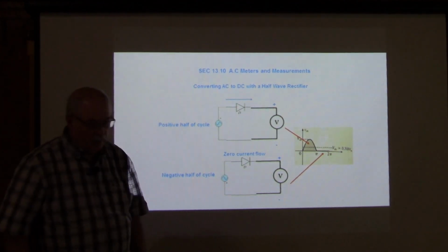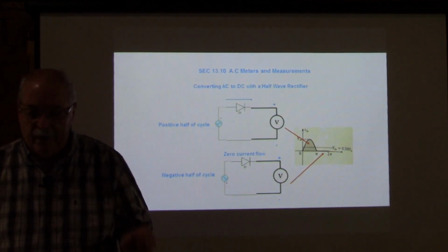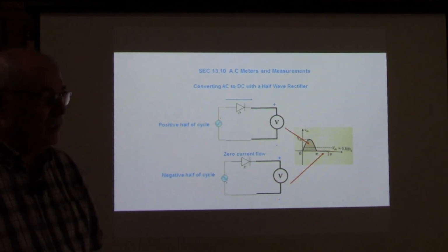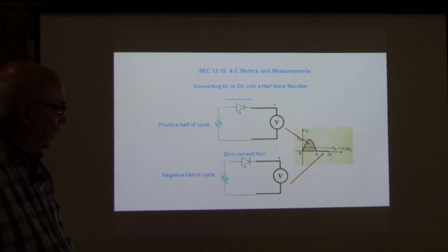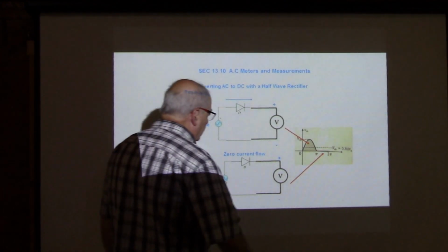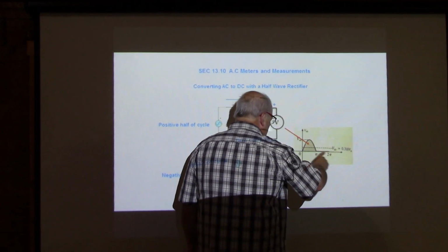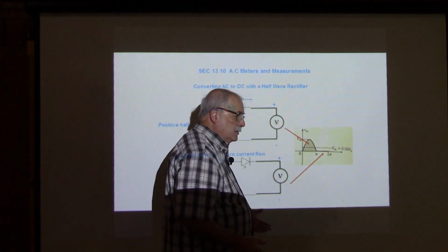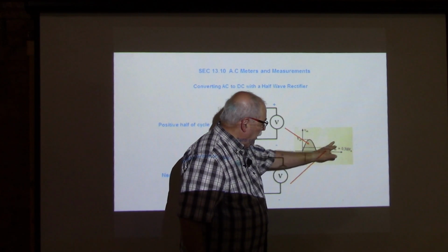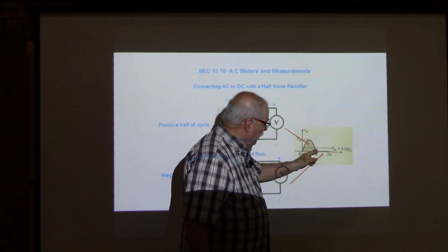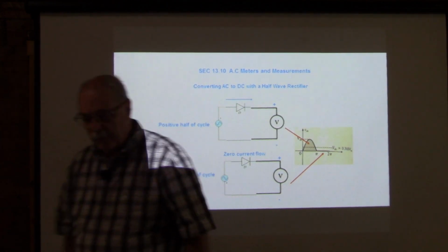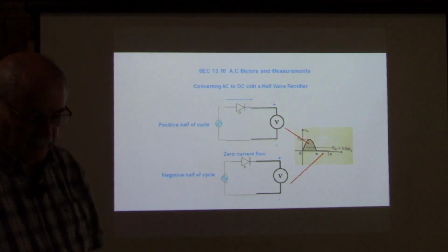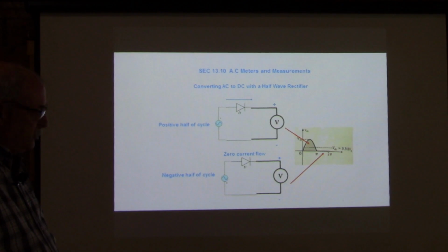So for half a cycle, the pulse average is 0.637, and if you run it over the equivalent of a full cycle, and the reason I show this example with the diodes is that this is an application for that, this would repeat. You'd only have a pulse, a space, a pulse, a space, a pulse, a space, and you only wind up with 31.8% of the output voltage.